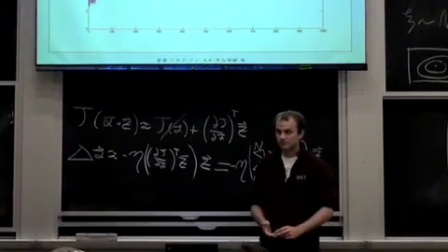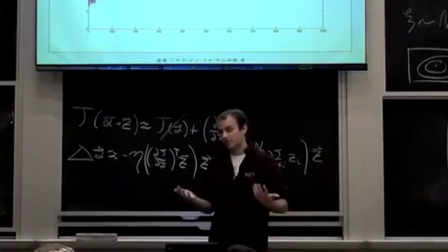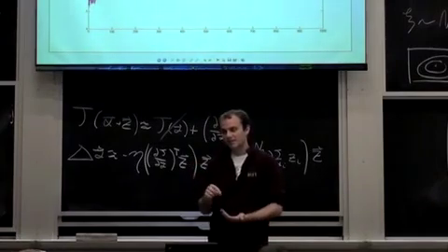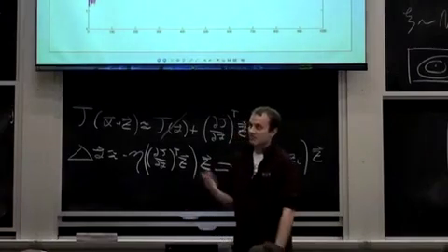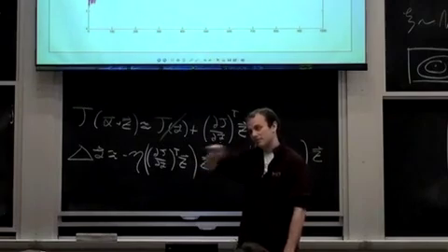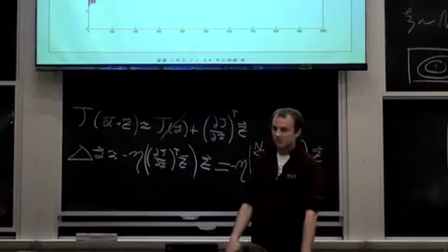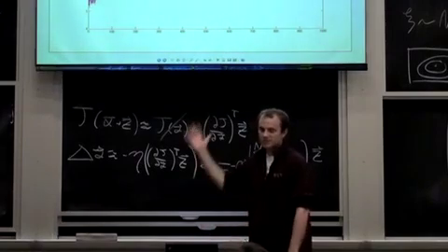What was the reward function? The reward function for this was the integral of velocity, of spin velocity, over the integral of power input. So it measured the force on it, multiplied that by the vertical velocity. That gives you the rate of power, right? And that gives you power, which is the rate of work. And then it calculates the distance. And so that ratio is what we try to optimize. So it tries to figure out the minimum energy per unit distance. It spins around in a circle, but it's a model of it going forward. So we did it for an angle, but you can do it just as easily with a linear test. It's just harder experimentally. Yeah, so it's an efficiency metric.